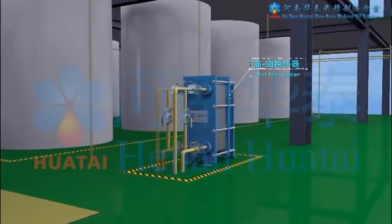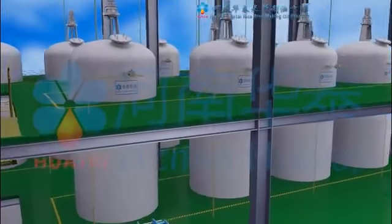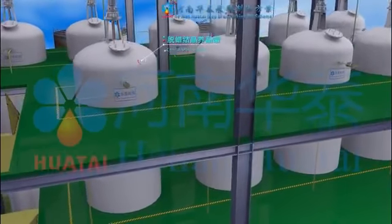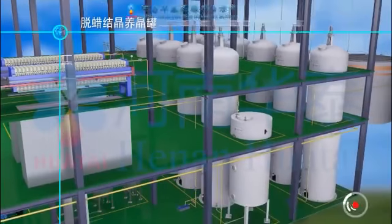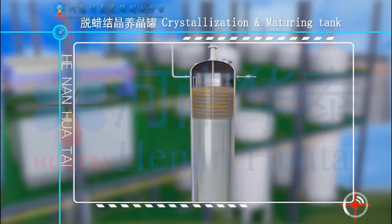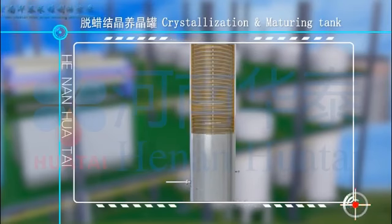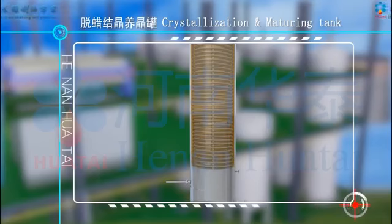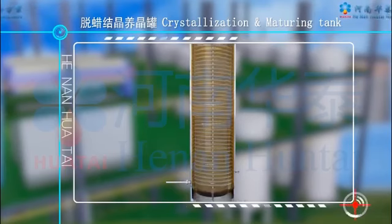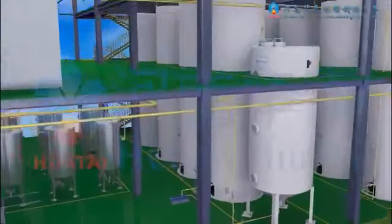The transport pump conveys the oil to the oil heat exchanger to exchange heat with the dewaxing liquid oil. After that, the oil enters the crystallization and maturing tank. The dewaxing crystallization and maturing tank is a vertical structure with a stainless steel snake tube inside to lower the temperature, matching with the PLC cooling curve to ensure the crystallization achieves the best effect.